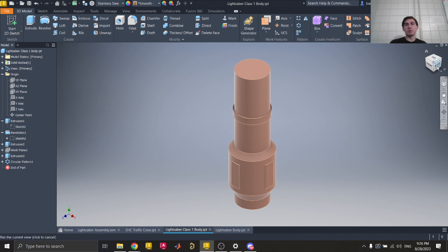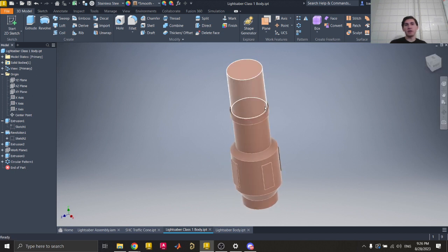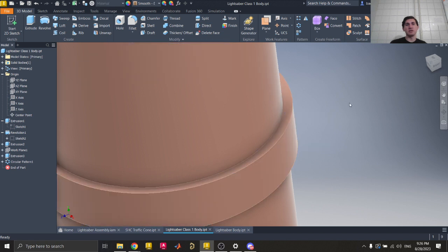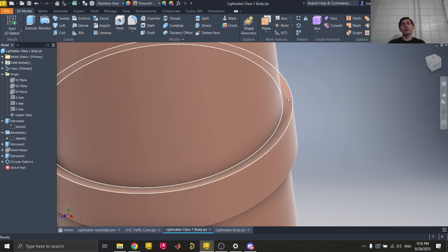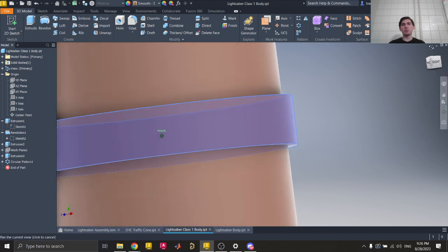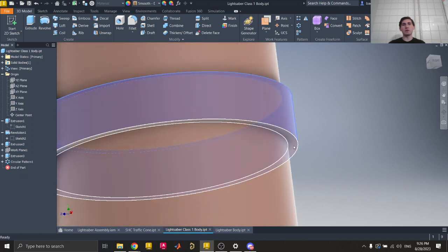So you can pick whatever colors you want, but let's say we want this little band in the middle to still be like a steel-looking color, something metallic. If I want to change just a certain surface to be a different color, I can just select that surface, and I can use the shift or the control buttons. Actually, let's see. Does it work for both? Yeah, so you can use the shift or the control buttons to then just pick multiple things.